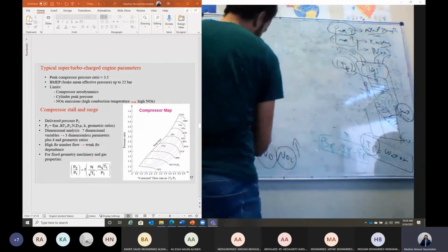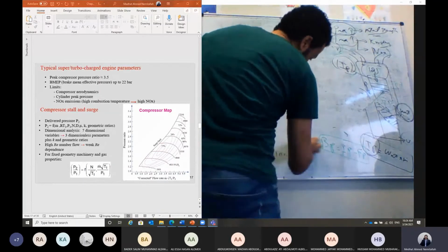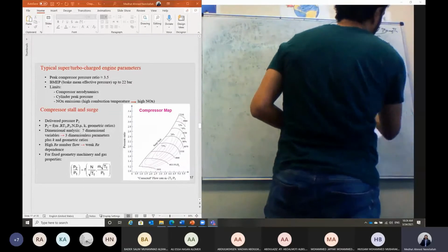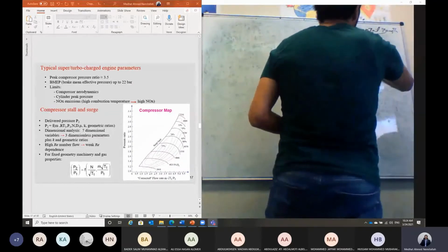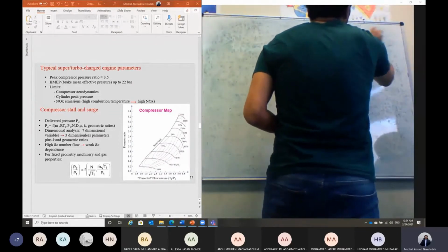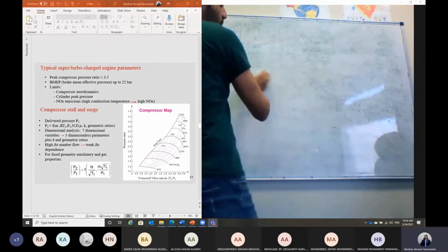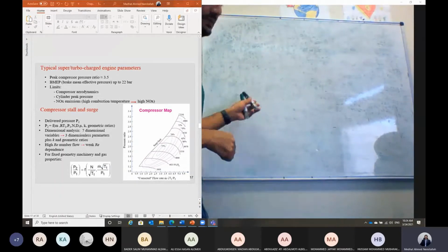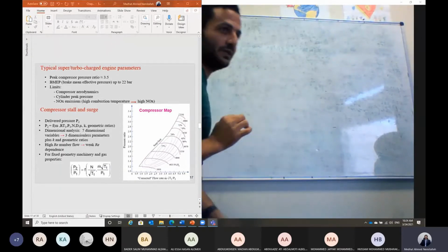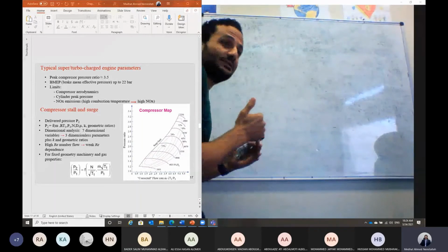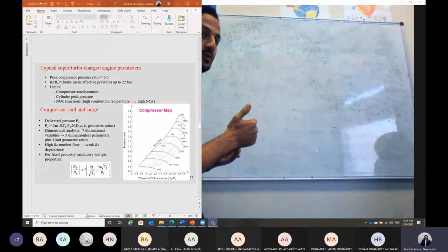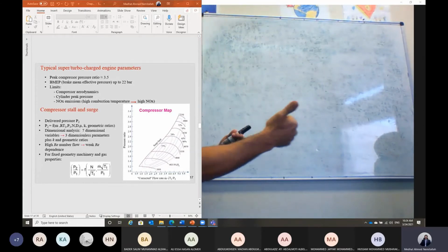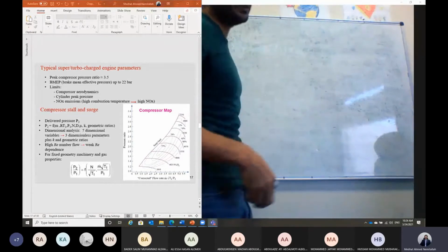So you have made a turbocharger to increase the engine power, but it resulted in an adverse effect. You are left with engine knocking in this case. That's why we said usually the turbocharged engine has a shorter lifetime. If you have a car that is turbocharged, it should have a shorter lifetime, because this engine is working at high burst pressure, which is more than the normal pressure it should be working on. High pressure, high temperature combustion means its longevity will be reduced.